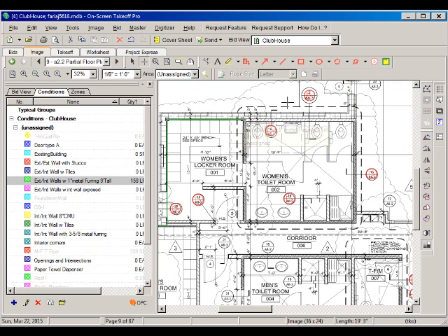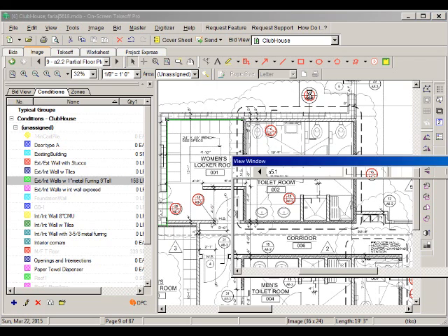Now this wall has interior exterior wall, but this has piping behind it. So this has the thicker area. This is going to have the 6-inch metal furring, or the 3 and 5/8, depending on what the architect says. Because it has piping, we are going to use the 6-inch.